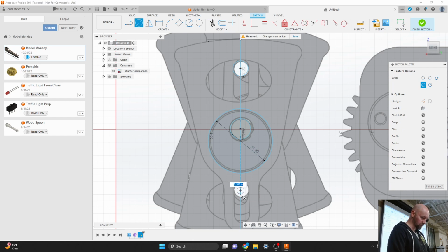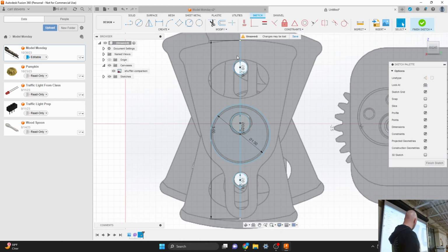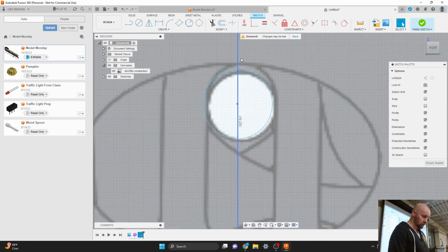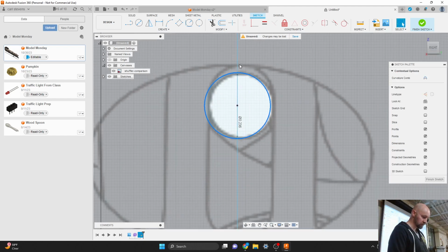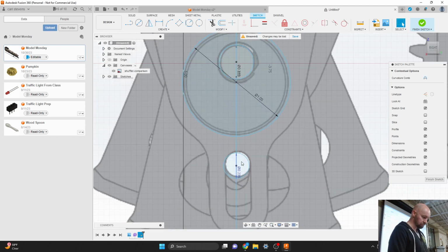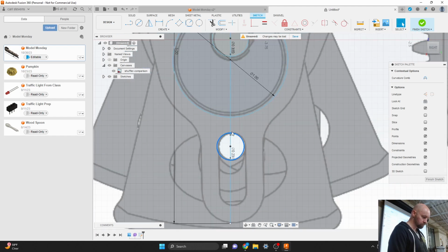Well, I was curious if there was going to be some sort of spacing that we could figure out. But I guess we're just going to... You can just do a 2-point circle for the top slot and for the pin in the top and the bottom, and then connect once you have those 2 circles. Even if it's not centered, I can shift it up and down because it's not defined. And just use a line to connect those 2 circles and build off that line.